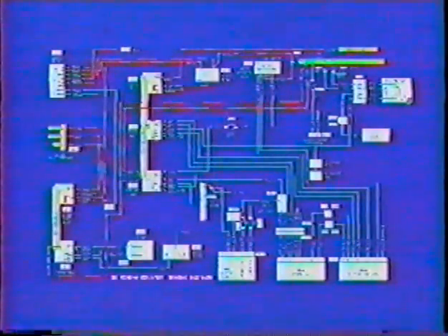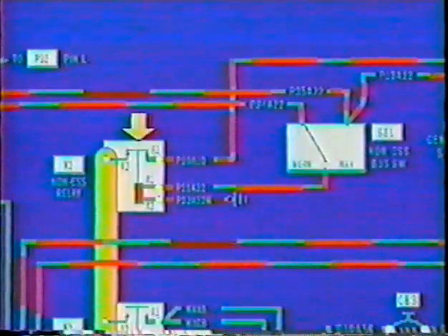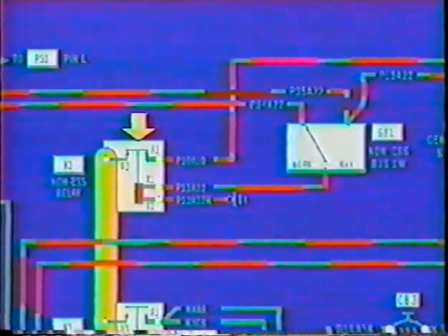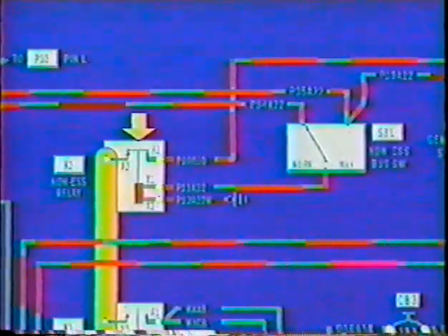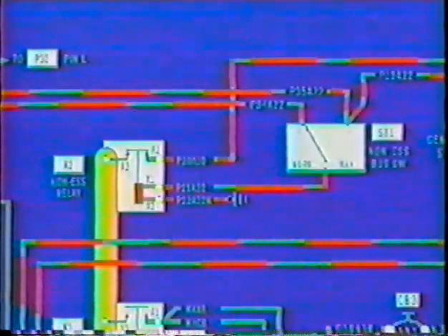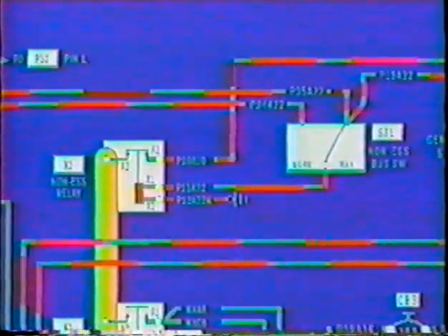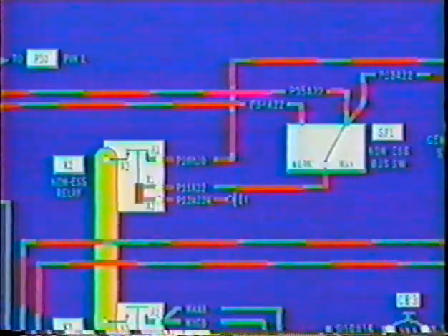Non-essential bus operation is now possible. Remember, the plunger is down within the non-essential bus relay, allowing the arriving external power to flow from A2 to A1 en route to the non-essential bus. Since the non-essential bus operation is possible in either the normal or manual position, complete the wire trace for operations in the manual position. Return to the overhead console essential bus.